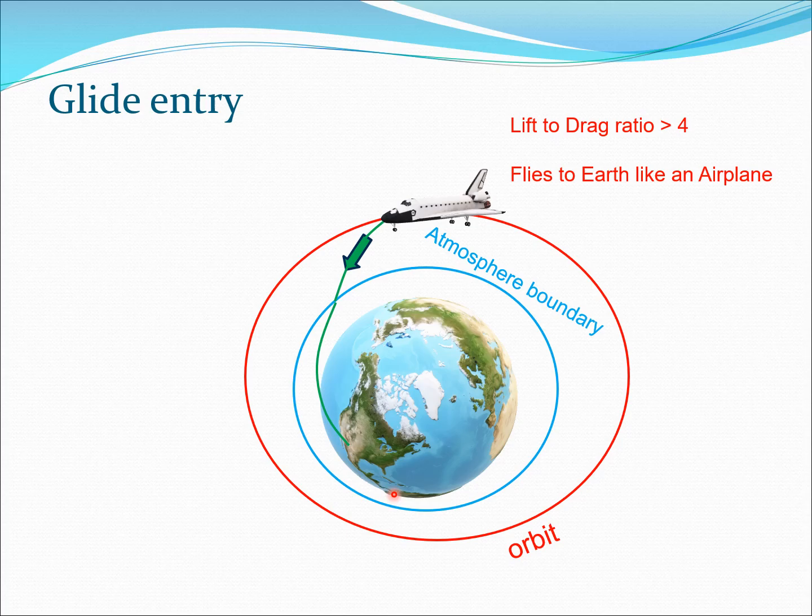So what happens in this kind of situation is that the first part of this landing, remember there is no air out here in the far reaches of the atmosphere or beyond this blue line which I have drawn. So in this region you can fall pretty rapidly, but as soon as you enter the atmosphere you glide, you essentially reduce this angle to a lower angle, and so you are able to fly somewhat like an airplane.